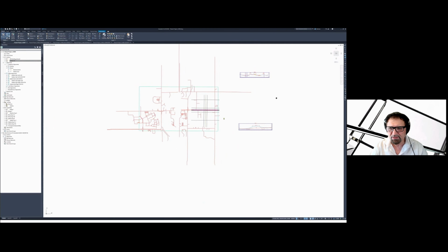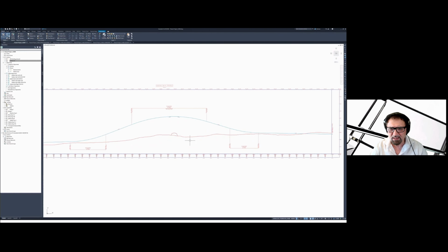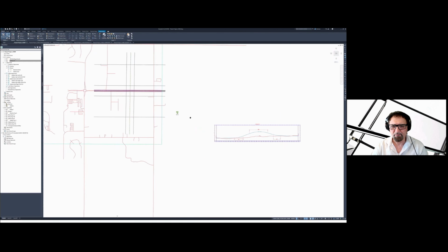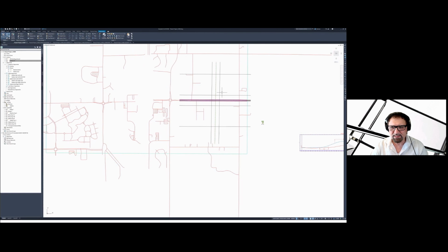This is then used to aid in design of the mainline alignment over the sideline by virtue of creating that surface model and including that in the profile. To check the clearances, I went in with 23 feet between the surface of the intersecting road and the alignment, which is the top of pavement for the main roadway. So those were the basic layout.